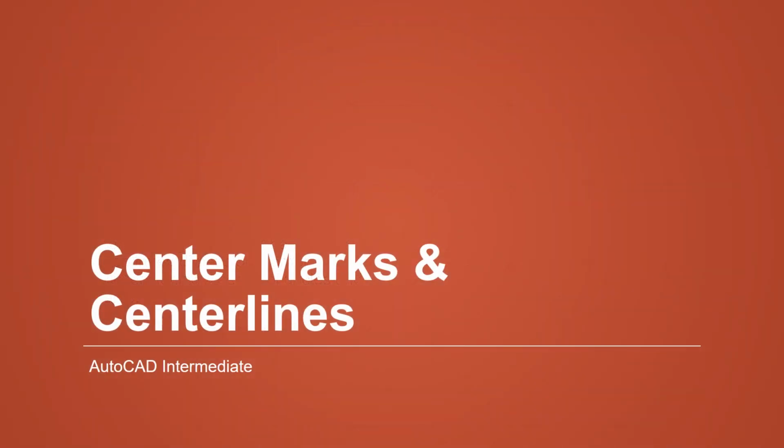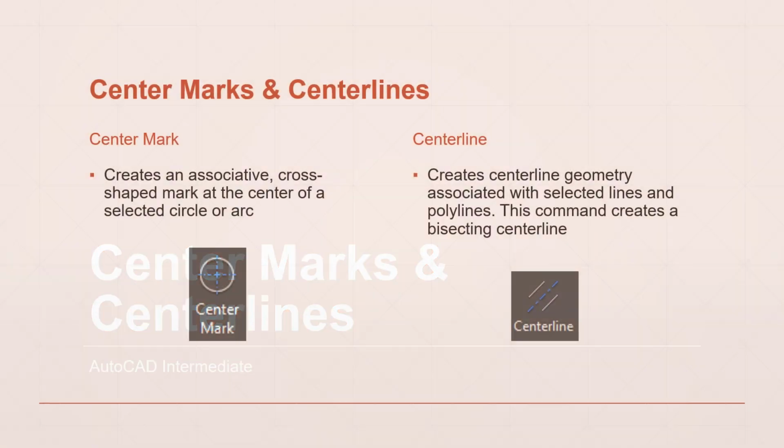The one neat thing here is the center lines and center marks that they've added. I'm so happy that AutoCAD did add these in. They make life a little bit easier for me and you both. In previous versions, we had to draw these center lines in and do extensions and set them up. Now all you have to do is say, hey, I want to put a center mark, pick the circle or arc that you want to put it on, and it puts it on there with no problem. And you can modify and manipulate it.